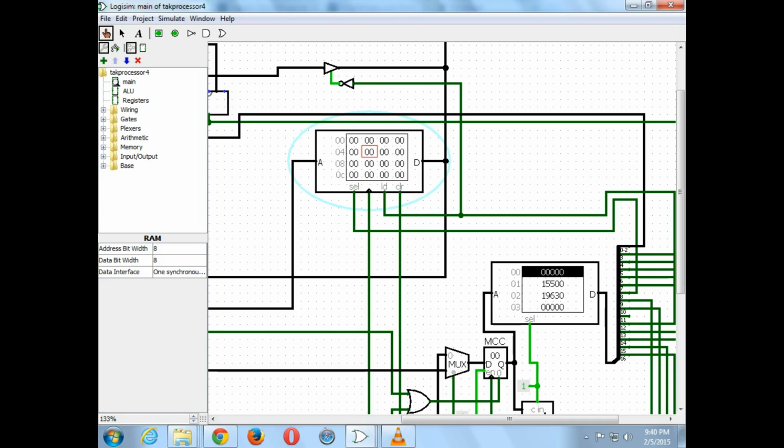But we really only want one of the memory chips to give its own location 23. That's why the select pin is useful. If you have 4 RAM chips, each has its own select pin, and the processor has a different pin that connects to each select pin.